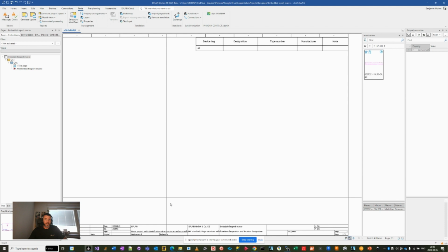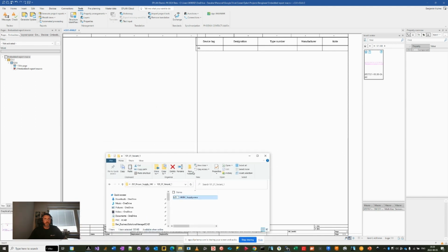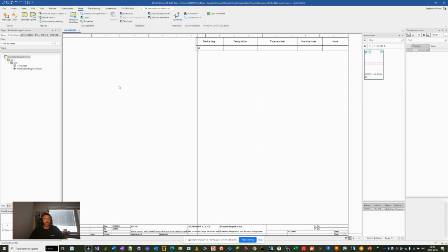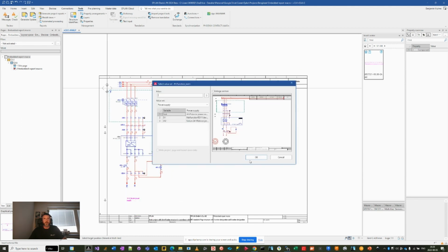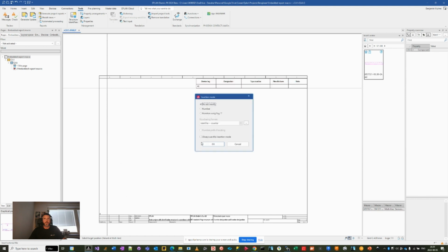I'm going to go to my macro library and see if I can find another basic macro to pull in here that maybe has a bit of part information. I think a power supply probably should. And just a note too, you can actually just drag macro files into EPLAN if you want to. That's kind of nice. And if I hit X and Y, it'll go to the original place that the macro was made. Of course, we have the placeholder options to select things. Do I want to number it? Okay, sure. I'll number it for this one. I'm going to drag those back.